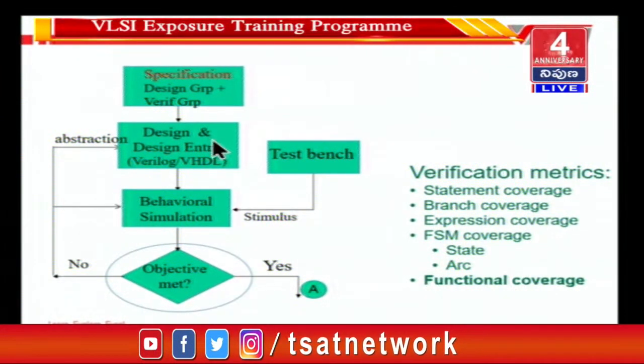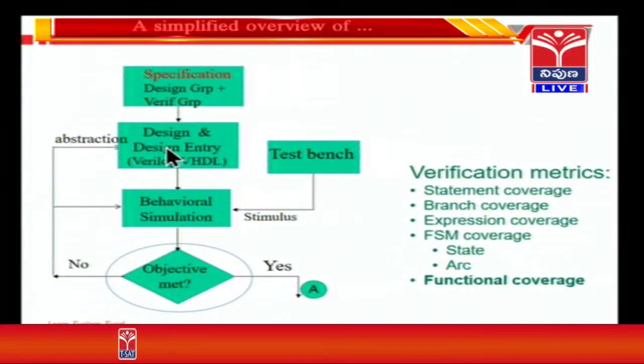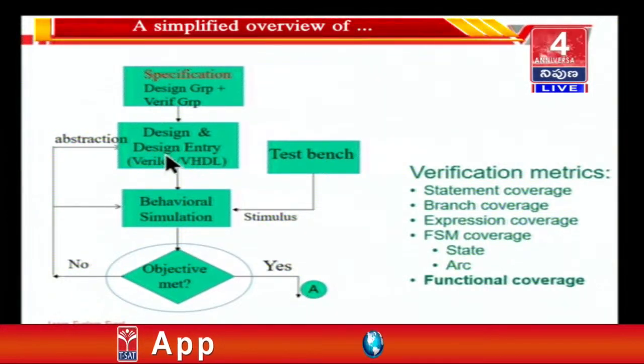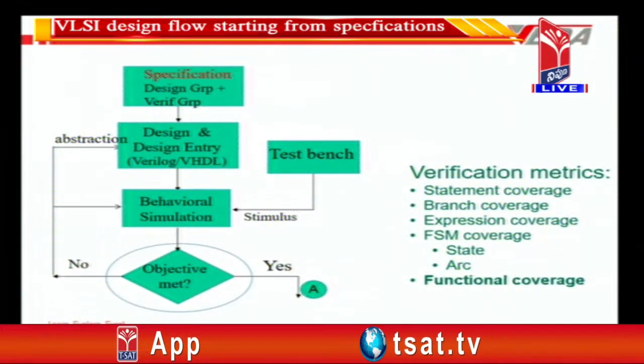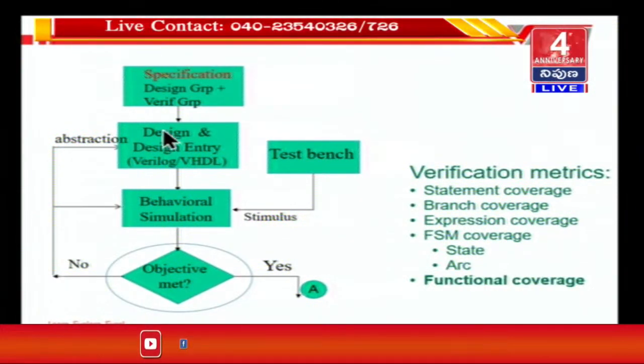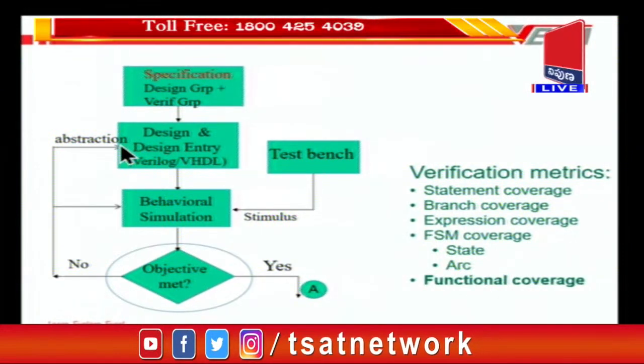Currently, not many designs are entered as schematics, only if the design is very, very small. It is much easier to write it in Verilog and pass it through the synthesis tool, so that the synthesis tool will generate the required gates and their interconnections, which adhere to the functional specification or the functionality of the block written in Verilog HDL.